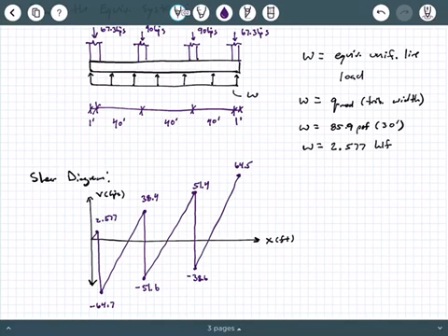And then we hit the last column load minus 67.3, which will shoot me down to a negative 2.78. And then guess what? We still have that 1 foot overhang right here. So we're going to say plus 1 foot times 2.577. And that closes nearly to 0. It should theoretically close to exactly 0, but due to some round off error, it may not exactly close to 0. So this should be kind of like anti-symmetrical with respect to itself.